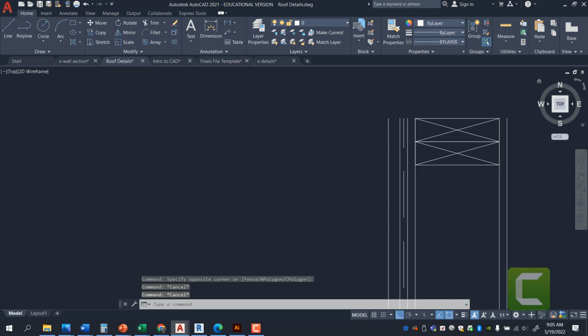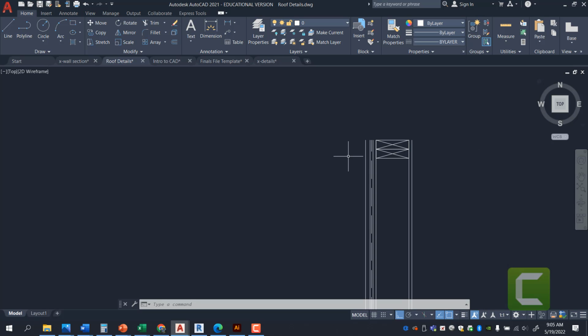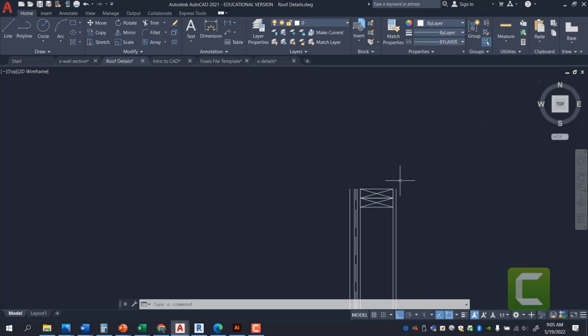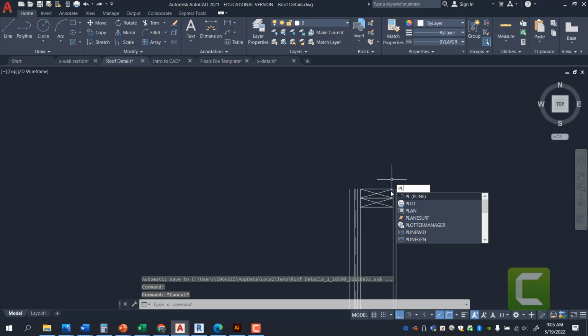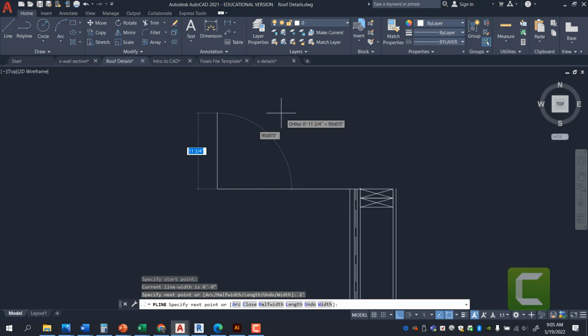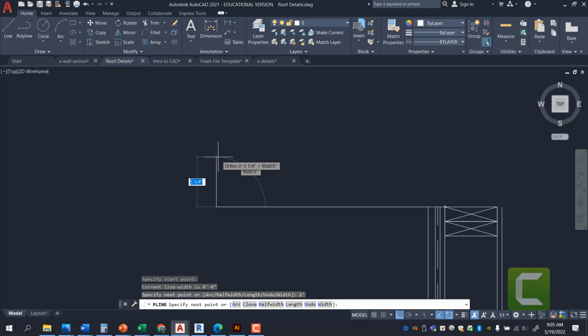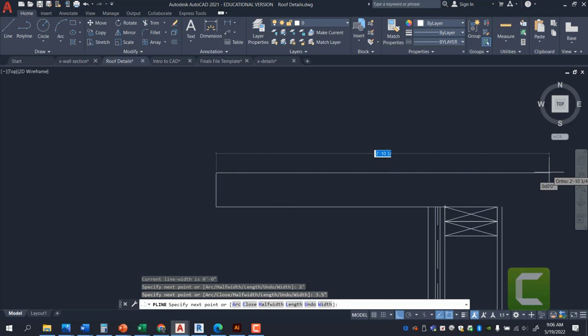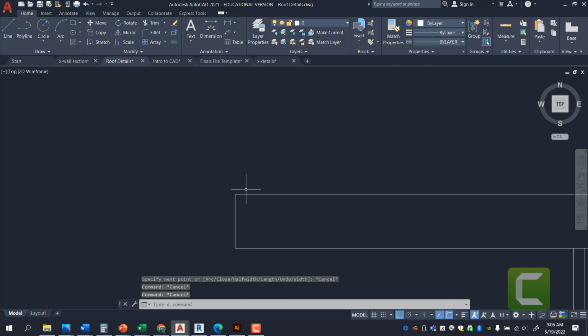So that's where your floor technically ends, or the top of your stud framing wall ends. Right on top of that is where your truss will sit. So I'm going to draw this line, and we're going to assume that where this truss lands, we have an overhang of, let's say, 2 feet. I'm going to go up 3.5 inches. Usually all your trusses are going to be made out of 2x4s, and let's assume a pitch of 3 in 12.